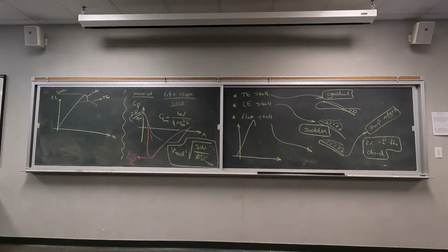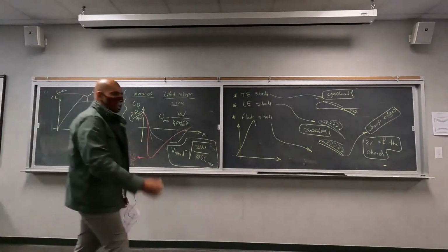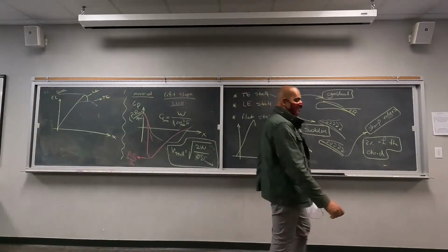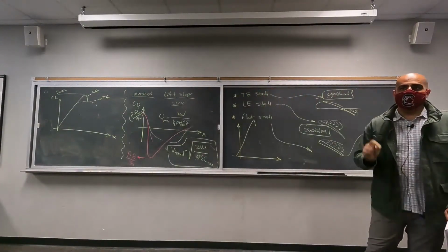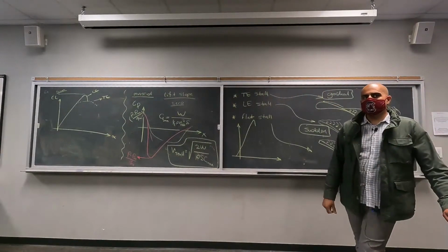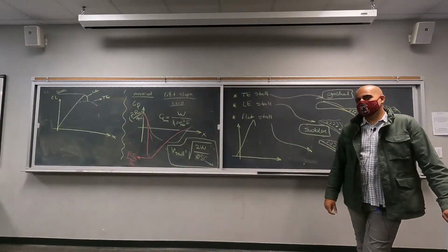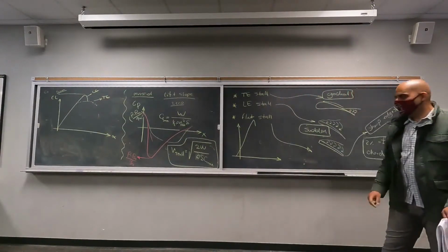Probably lower, but still has a sharp decrease like the leading edge stall. It is lower, that's true. But what was the reasoning? It probably has a sharp decrease like the leading edge stall does afterwards. Mm-hmm. That's correct. So essentially, all of the flow is going to separate from the flat plate. But why is the lift coefficient lower? I actually mentioned this very briefly when I was talking about it.